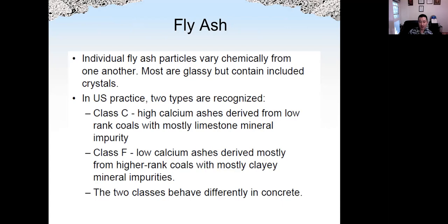The individual fly ash particles will vary chemically from each other, but most of them are glassy, but contain some crystals. Glassy here means the chemicals are reactive, so we want more glassy phase in fly ash, because the more glassy, the more reactive the fly ash. The more crystals, the less reactive the material is.